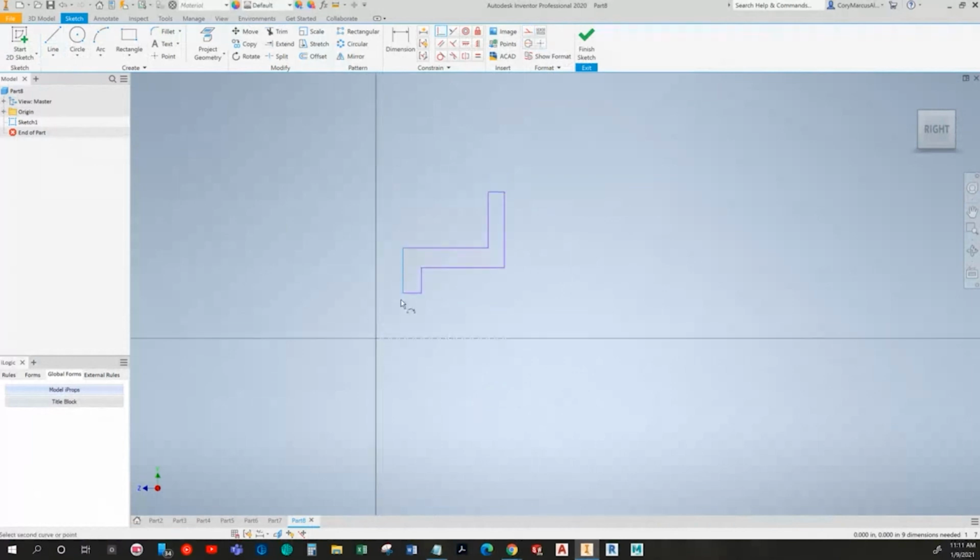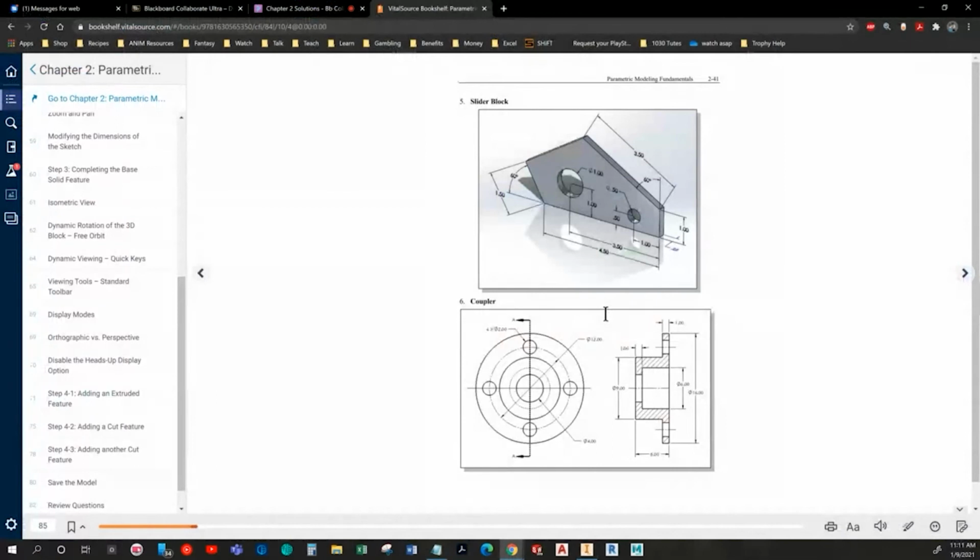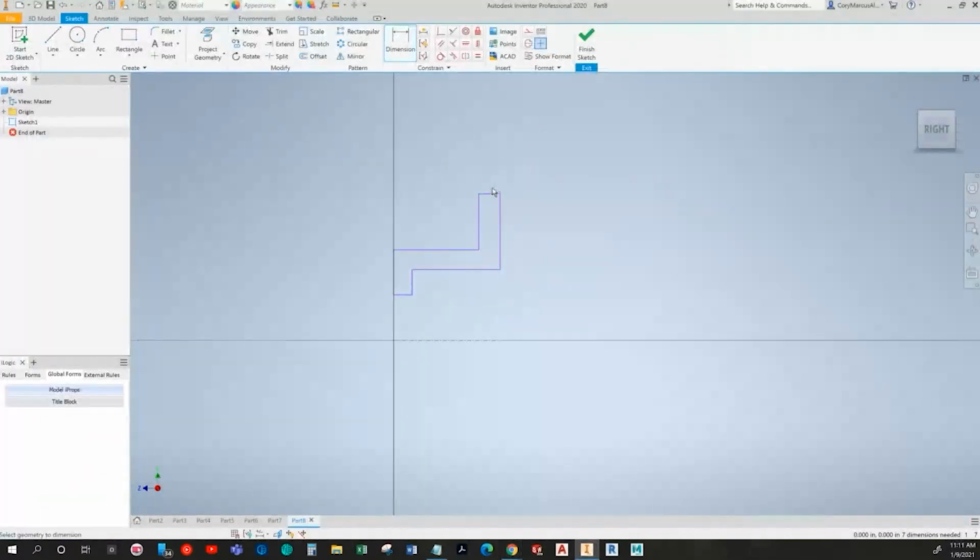So I'm going to choose this line and make it coincident to this point, so that now that line is in line with it, I don't have to worry about it shifting to the right. This part will, but not this line that you see is turned black. In the same vein, I'm going to do the same thing on the other side, and this one I'm actually going to be controlling the line more or less. Once we have dimensions in, I don't want this line to be the only thing that's not defined. And I'll show the importance of the center line in just a second.